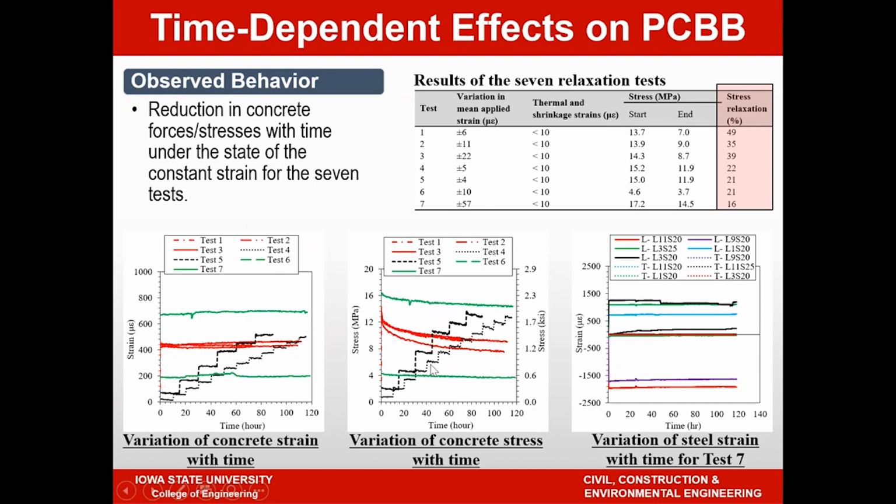The second figure shows the relaxation losses in the green and red curves. The black curves don't quite indicate this because the actual target line was much higher. The values that you see here are after losses, but one thing to observe is that between each step you can see the drop in stresses, which is because of the relaxation taking place in that member.